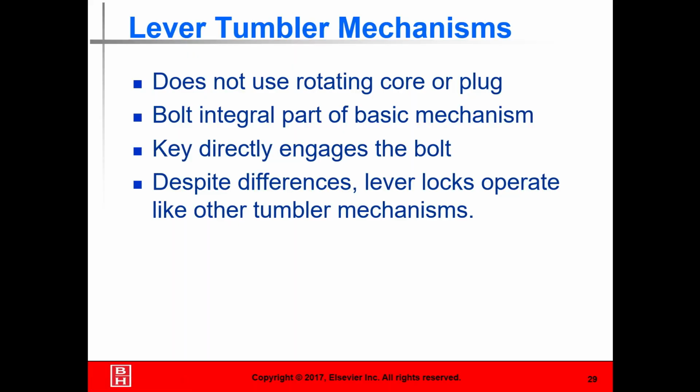Lever tumbler mechanisms are very similar to the pin. Unlike the pin or disc tumbler devices, the lever does not use rotating core plugs, and the bolt is integrated in. It's the only other type of mechanism in which keys directly engage the bolt.